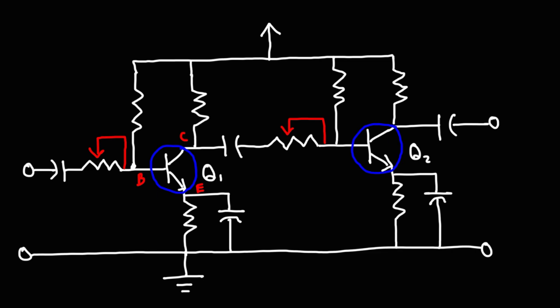Now, in this video, we're not going to focus too much on the math, but more on the concepts behind this particular circuit. Now, the first three capacitors that you want to be familiar with are these three capacitors, C1, C2, and C3. These are coupling capacitors. They're designed to block DC, but to allow the passage of an AC signal or a voltage variant signal.